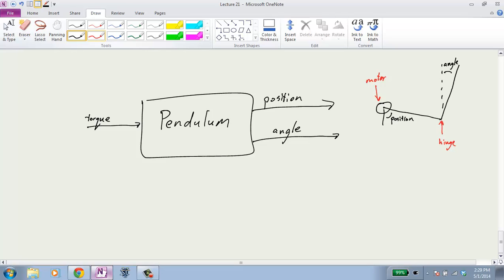So we'll see that here as I build this thing. In this block diagram, I'm not going to explain too much. It's sensing the outputs, and it's feeding back the velocity into the motor itself. So when it's on, like it is right now, you see it slides a little better than it did when it's off. I'd like to increase that feedback and make it seem even more frictionless. We can do that by changing a little variable here. The feedback was at something like 70. We can go to 80.